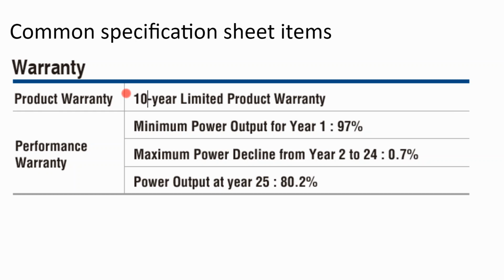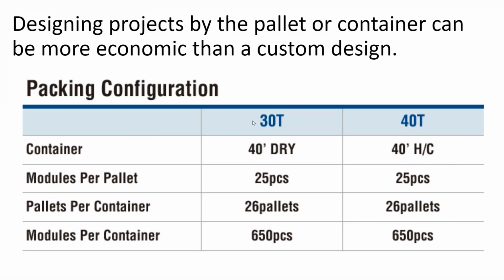And the top shelf manufacturers do offer 25-year warranties on their panel, and the price difference between the mid shelf and the top shelf very well might be the value of that warranty. And so it's really up to you at that point: do you add another year or two onto your project payback and go with a longer warranty item, or stick with something cheaper? And it could completely depend on the client and the job site on what's the best choice. In my experience, rooftops which are not easy to access should be treated with a longer term perspective than rooftops where you can easily get up on the roof and back down again.